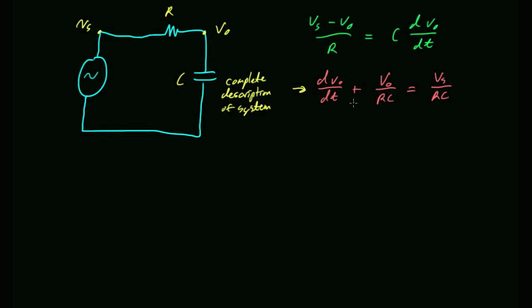There is a time domain approach to answering that question, and there is a frequency domain approach to answering that question. This differential equation has everything built in it to answer the time domain question. What's your output in response to a particular input? You don't need anything else than what's here. And the other bit that's interesting is that it's entirely characterized by the value RC, the time constant. If you know the time constant, that's it. That's the only parameter of this system.